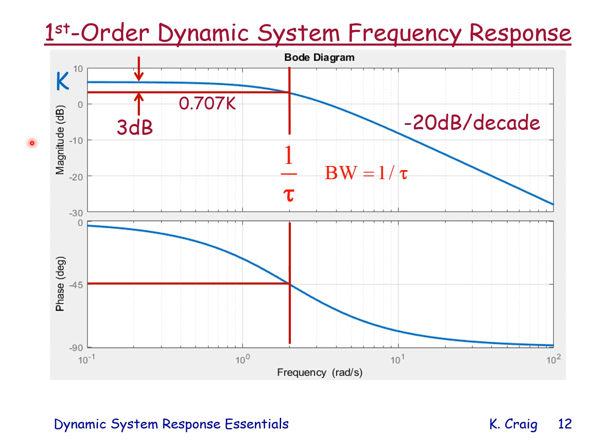So if I put in sine waves of different frequencies, and I plot amplitude ratio, output over input, in decibels, where a decibel is 20 times the log to the base 10 of the number I want to convert to dB, and phase angle in degrees, if I plot those points for varying frequencies, I get what we call the frequency response plots, or the Bode plots.